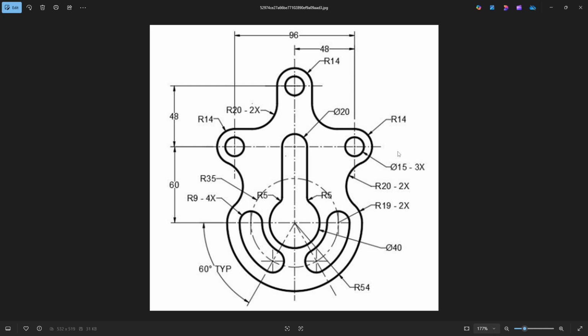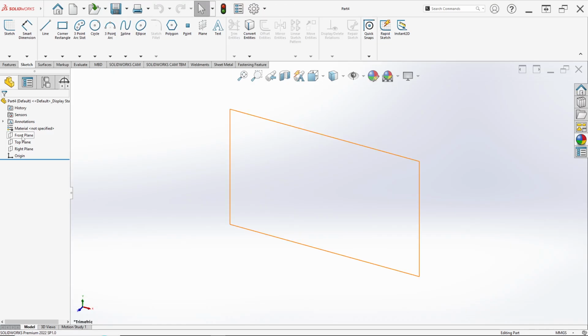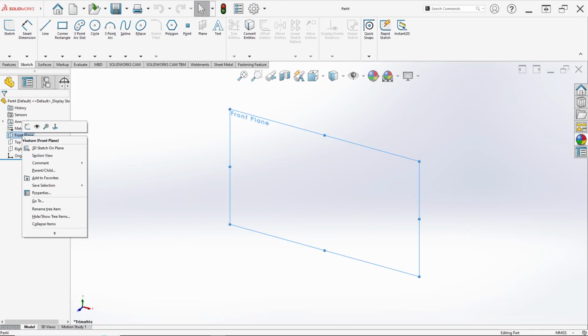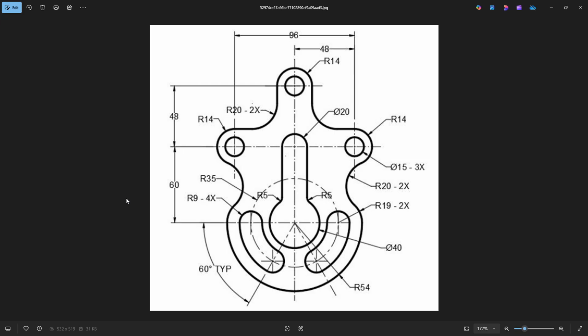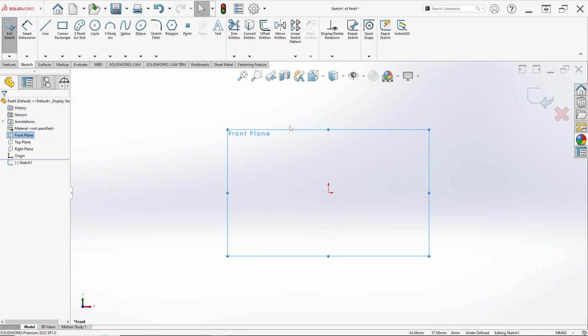In this occasion, we will learn how to design a simple path in SolidWorks. Okay, let's just start. First, you want to make a sketch from the front plane. Just right click on the front plane and click sketch, like this. So we want to draw from here.